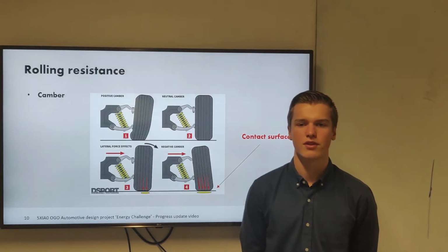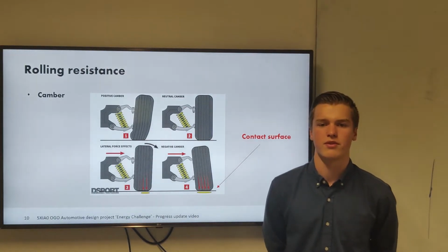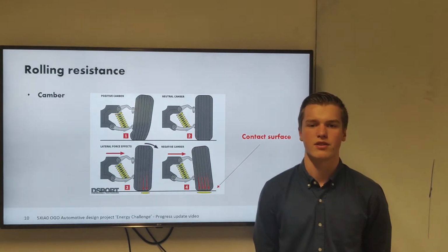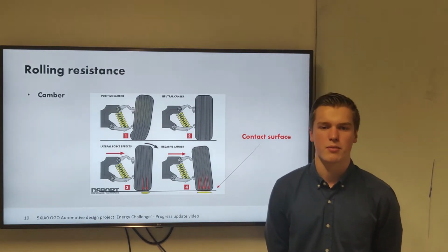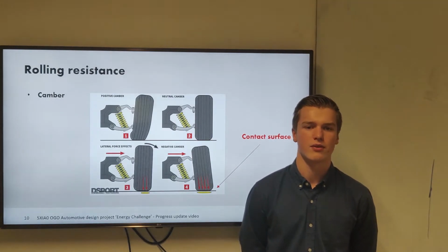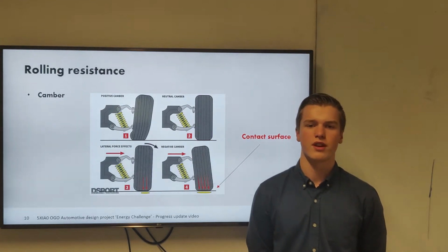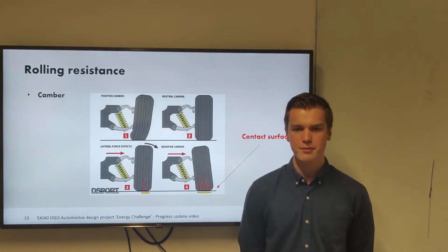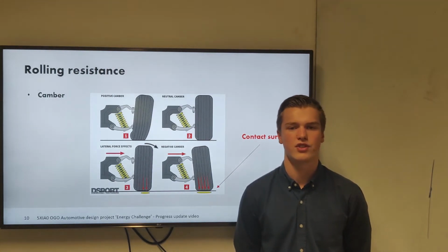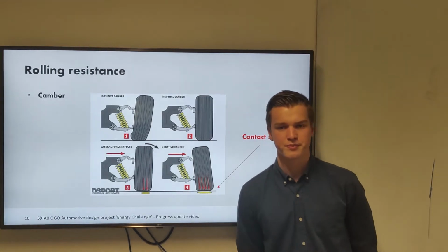We will execute the coast-down motion several times. Also, we will adjust the amount of camber during the experiment and check the data by inserting the SD card into the laptop. In this way, we can also check if the values are realistic to be sure everything went well. These values will be used to calculate the optimal driving strategy in terms of efficiency.